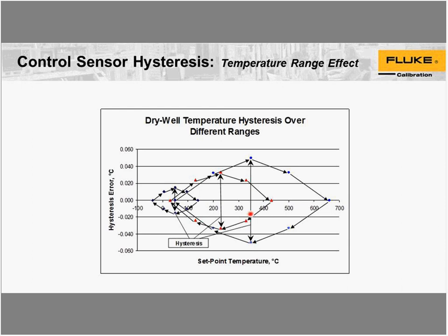And scale that up and down at least 10 times, validate it out, and you can take averages of the variations, particularly at this midpoint, that would anticipate a hysteresis situation. Now, if you're using an external reference thermometer, and your external reference thermometer has little or no hysteresis, it won't be a problem.